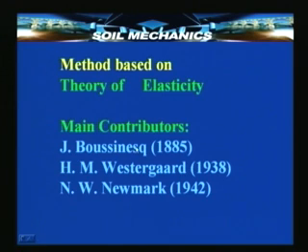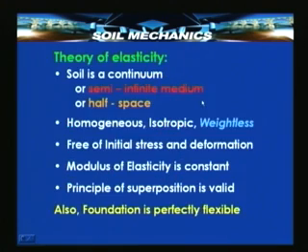We shall be seeing today Boussinesq's theory of stress distribution, which is essentially the application of the principles of theory of elasticity to the problem of stress distribution below a foundation resting on a soil. Let us first try to see what this theory of elasticity is all about before we see how it has been used by Boussinesq in computation of stresses. The theory of elasticity, as the very name suggests, is based on the concept of elasticity. What is this concept of elasticity? What is an elastic material?